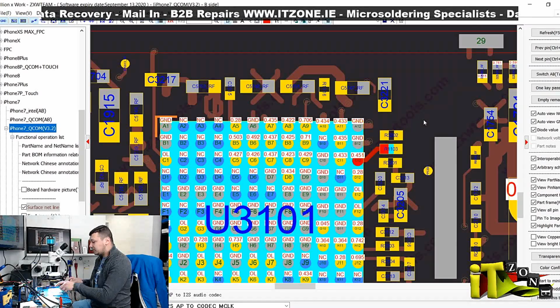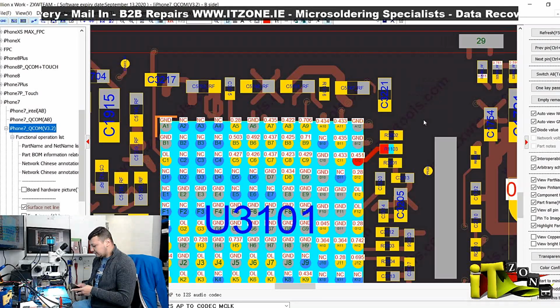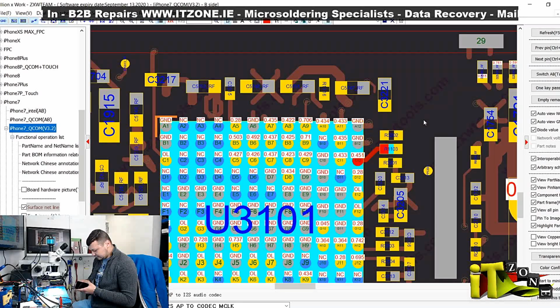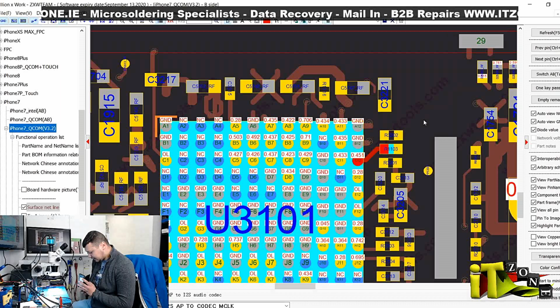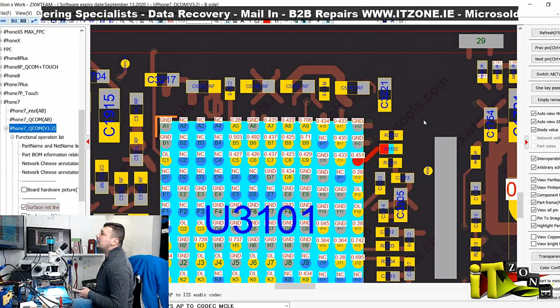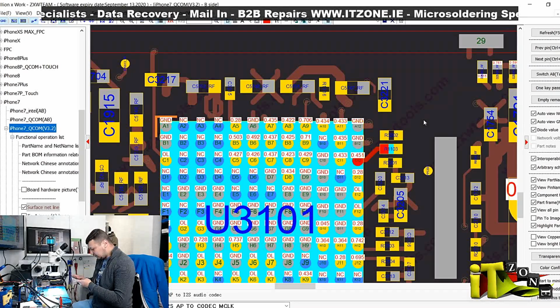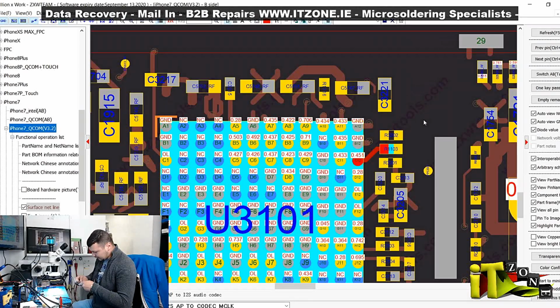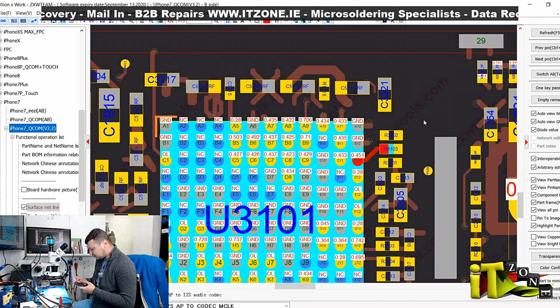I'm just gonna remove the motherboard, and all we have to do in here is remove the codec, run a jumper from the R1103 to the pad C12, and we should be good to go.